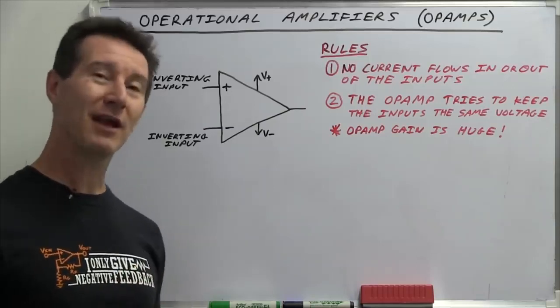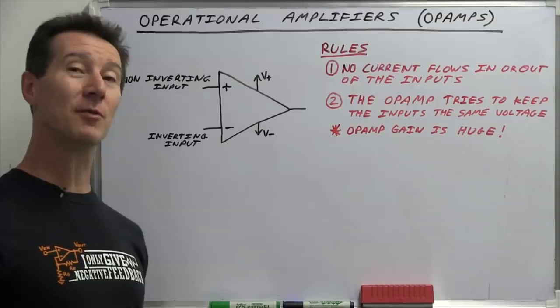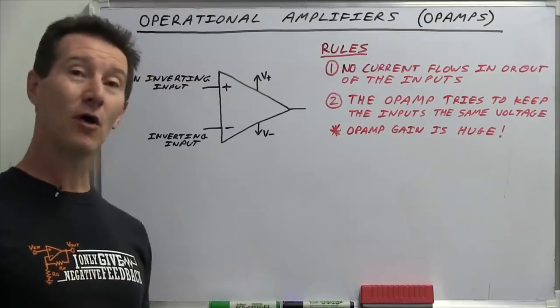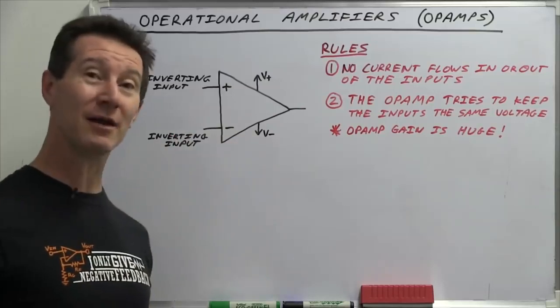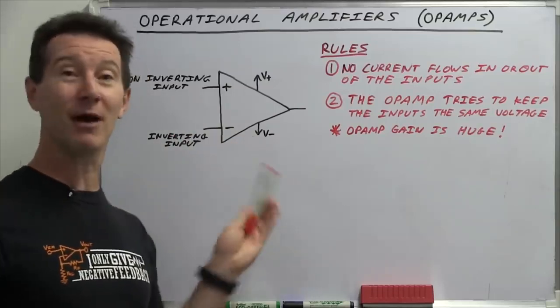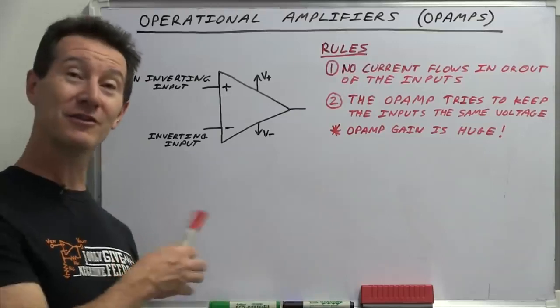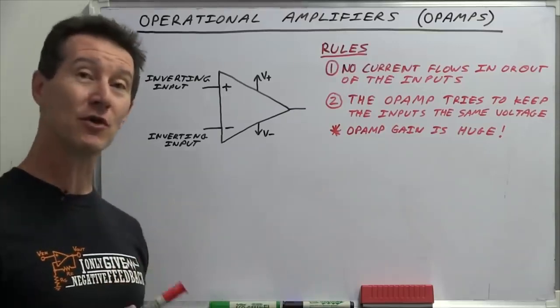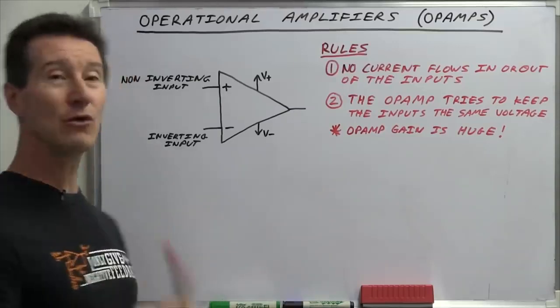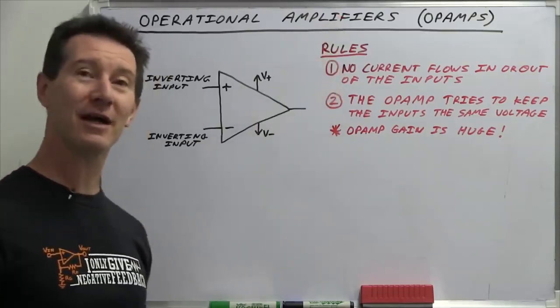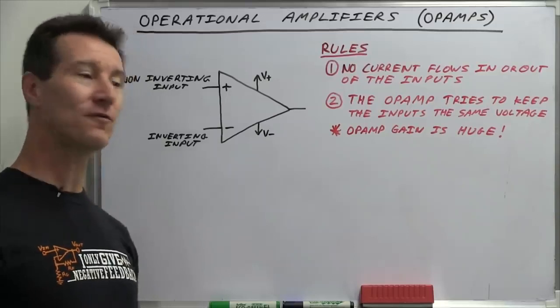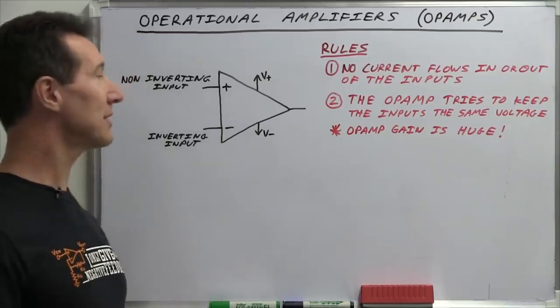So although we don't have analog computers today, we still use them for those mathematical operations. You can turn an op-amp into an integrator, for example. You can turn it into a summer, which is just an adder, and things like that. So they're really useful circuit building blocks. But the main thing we're going to look at is the operational amplifier as an actual amplifier, because that's what they're most commonly used for, and probably what you'll mostly use them for as well.